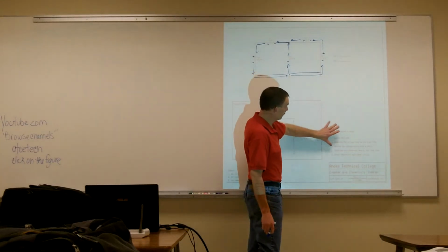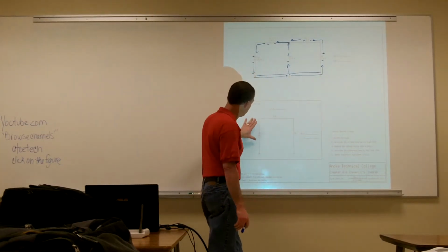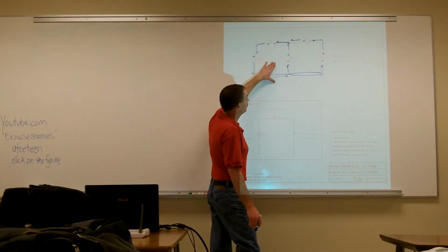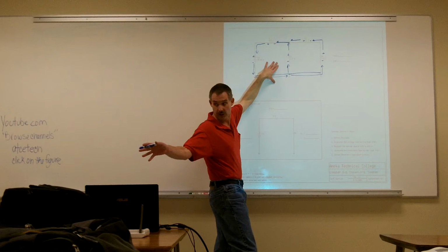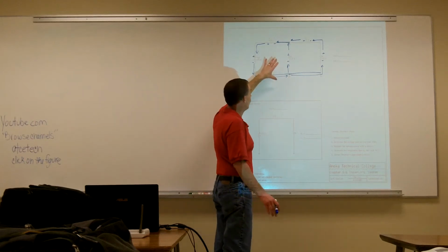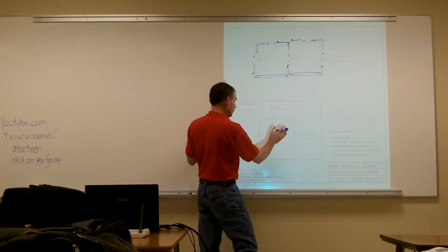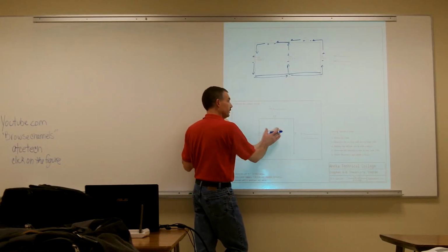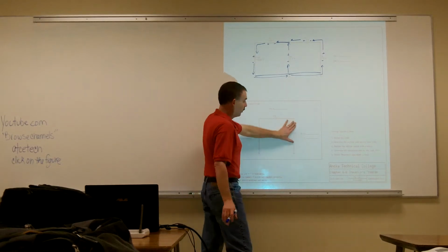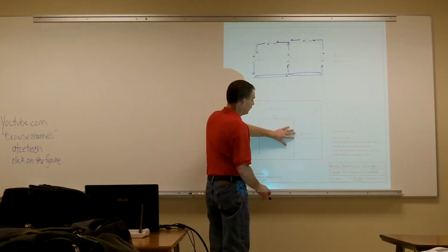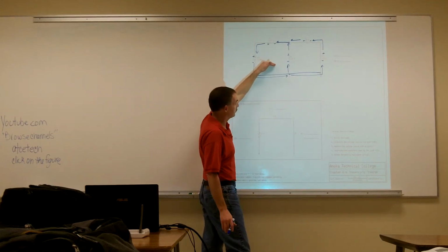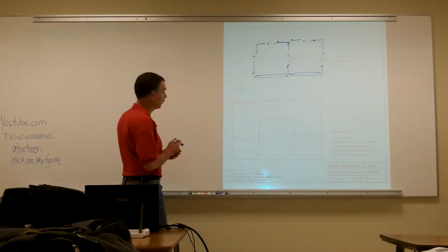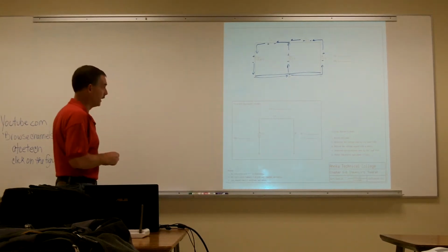All right, so to come up with an equivalent circuit, we can take this circuit, whether it's as complex as the WaveTech or as simple as this circuit, and reduce it all down to one voltage and one resistor. No matter what I do to the load, it'll act the same way as if I were to put it into this circuit. So I can reduce it down to just one voltage source and one resistor, and have it react the same way.